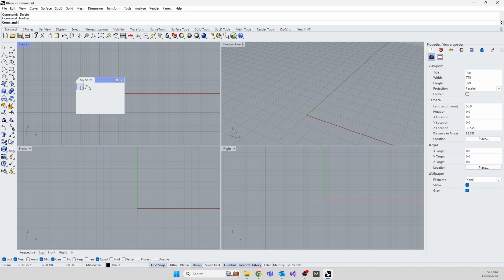This one over here, I'll delete a little bit later. So I do want line, I use it a lot. I want the circles because I use it a lot. So I'm going to hold the control key, left mouse button, and I copy circle to here. What else do I use a lot? I use split and join and edges. I want to show edit points. So that one I use a lot. Copy and put it down in there. Explode, we use a lot. And join, we use a lot.